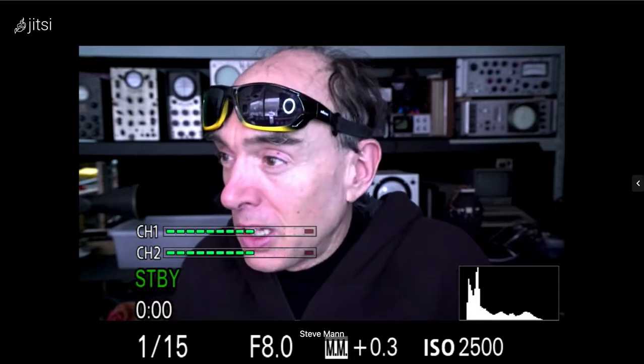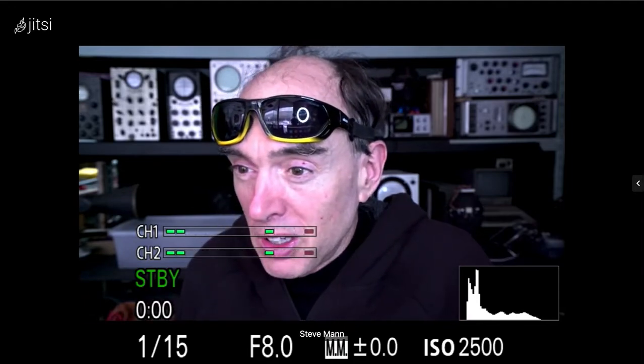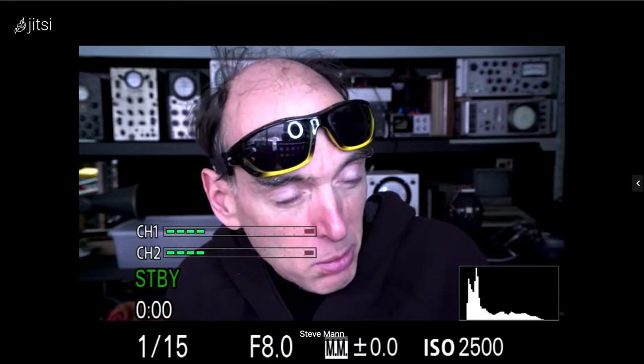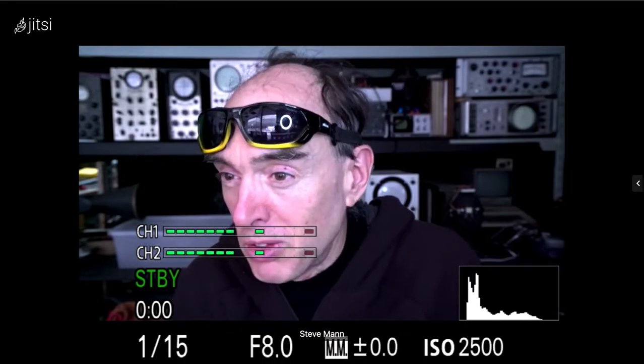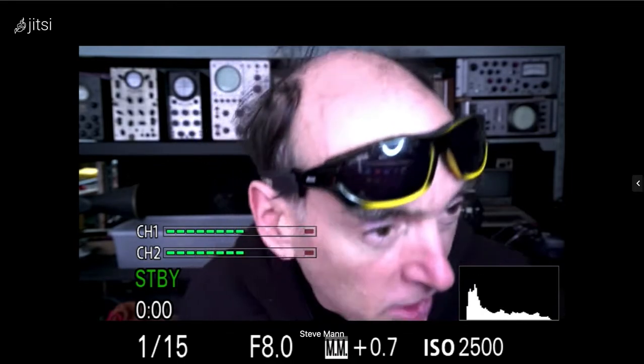So if our boat's moving at a constant speed, there'll be a constant sea clutter or lake clutter or whatever background. And then of course there are objects that are stationary, and there are the waves that are accelerating a little bit, but then the ice has a unique appearance, as it's a single or a small number of pieces of ice that are moving at well-defined frequencies, maybe one or two pieces that are moving. Each of them has a chirplet component. So with the chirplet transform, we can resolve it into these different components and see each of the chirp functions.